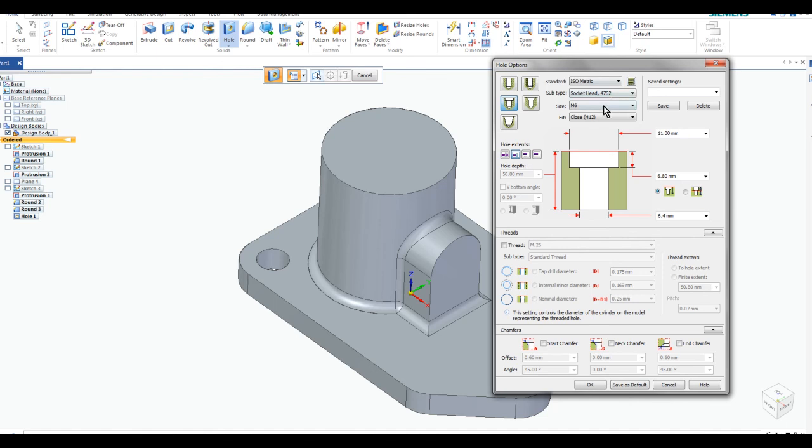Okay. And in this particular instance, we're just going to type in the values. All the values are located on the section view, so the through hole is going to be 30. The depth of the counterbore is 16, and the counterbore diameter itself is 40. Okay.